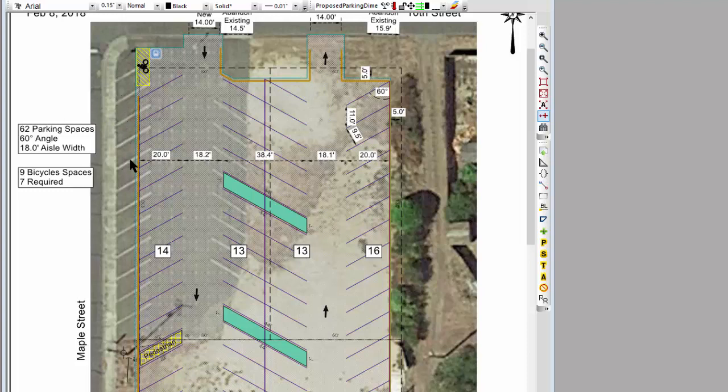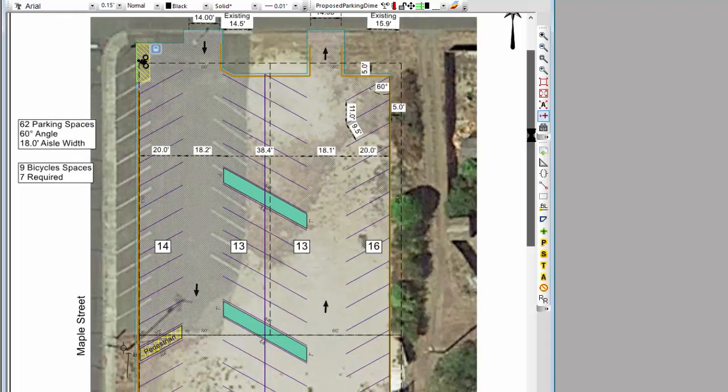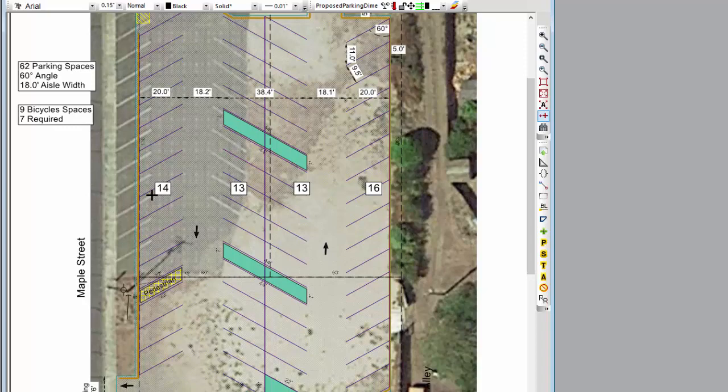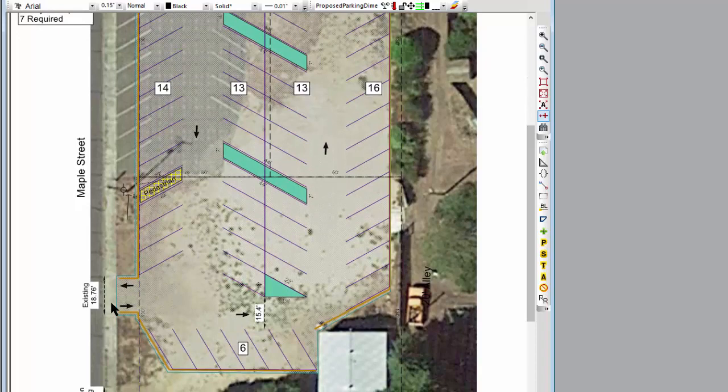The city wanted us to pull out this existing pavement here, and we wanted to comply with that. So that further reduced it. I really was stuck with this 60-degree parking layout and played around with some others, but ended up here. Once I knew that's what I was going to do, I could come in and lay out my 4 rows here. If I'm going to end up using this existing curb cut, I probably could pick up 1 more row down here. Well, once I had done that and met these requirements, I now pretty much had my paved area.